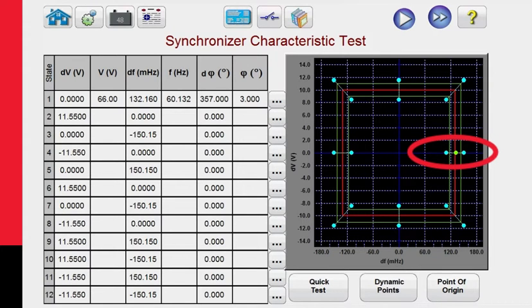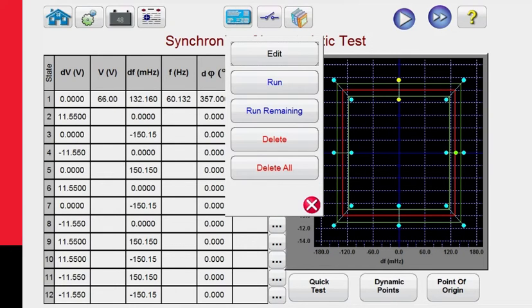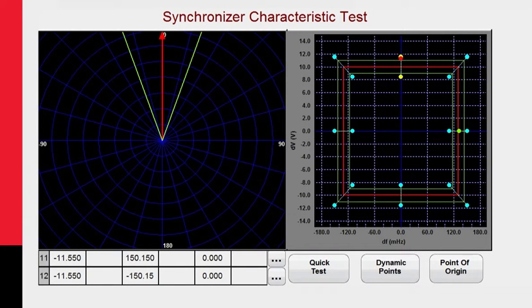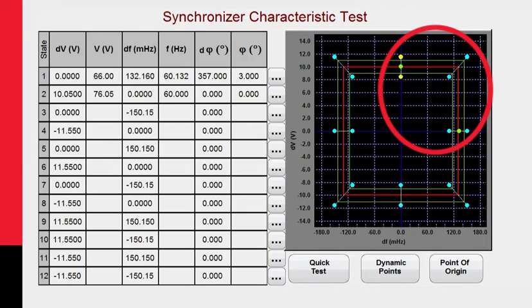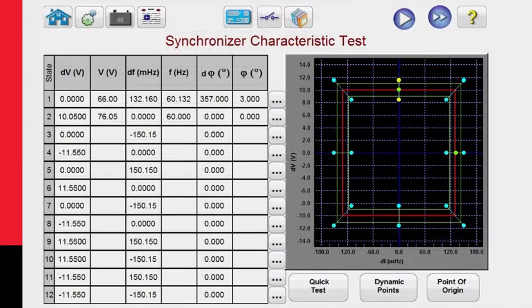If we want to ramp, for example, in this case, we're going to ramp this particular test right here, and you can see it's ramping the voltage, changing, and when it hits the operating characteristic, you get your green test result. If it operates outside the characteristic, well then it'll show up as a red X.